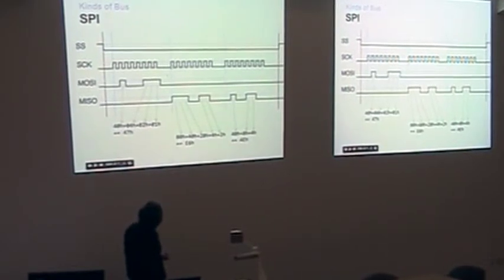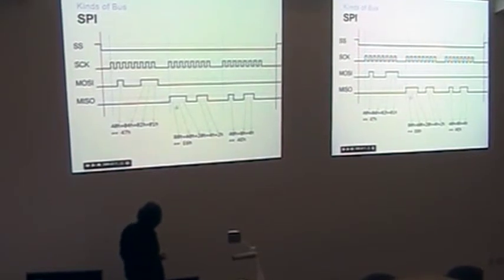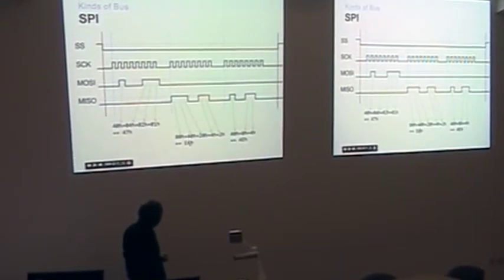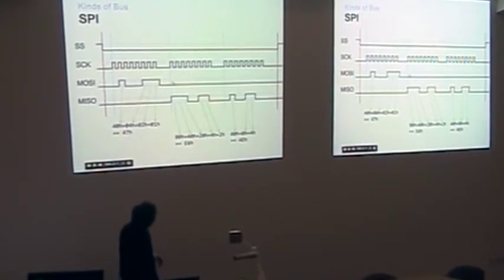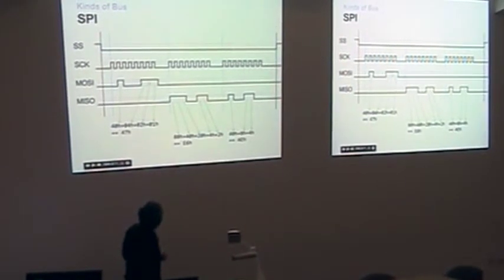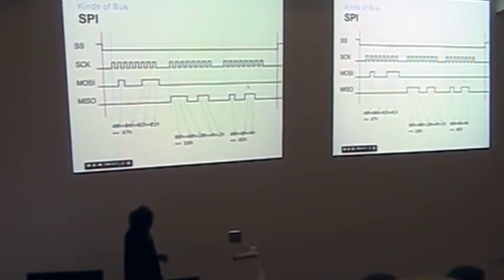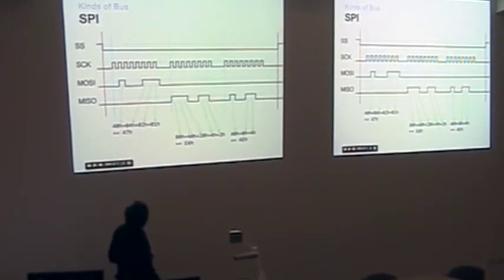And then maybe we'll shut up now, and we'll just pulse the clock line again, and we will see if the slave says anything. That is, the slave said B6, 4E, some arbitrary numbers I picked. And so this is a typical example of something that might happen over an SPI bus. The master here is always in control of the clock. The master is always outputting something on MOSI, and if it's got nothing to say, it usually just says 0. Because half the time, you're wanting to read something from a device, so you still have to send the clock anyway, and just hope that it said something on return.